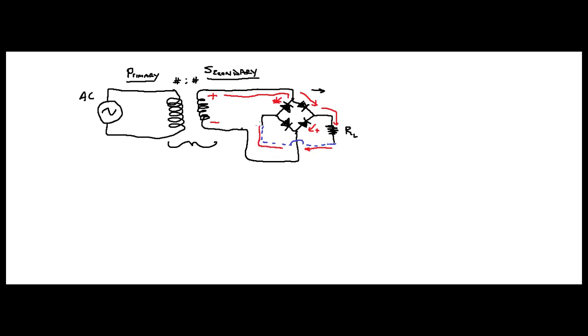Back up here. Now it's going to come back here, and it has to make a choice. Now think for a second. Your potential, your voltage at this point, whatever you started with, is going to drop by one diode drop, which is 0.7 volts here.